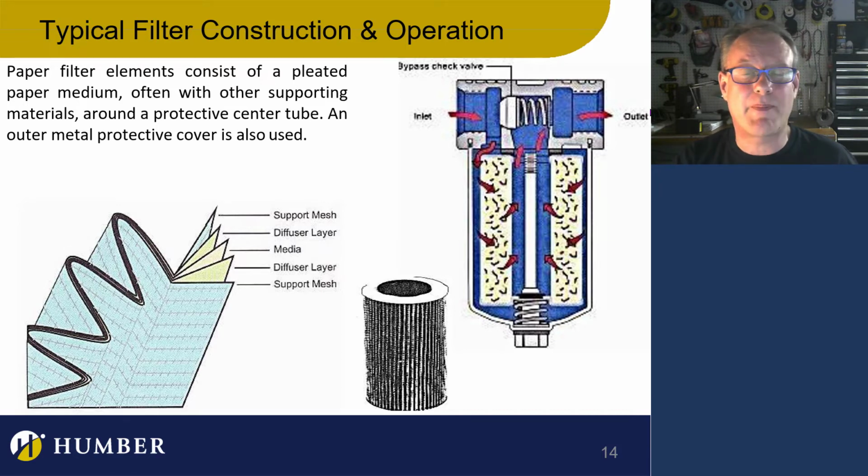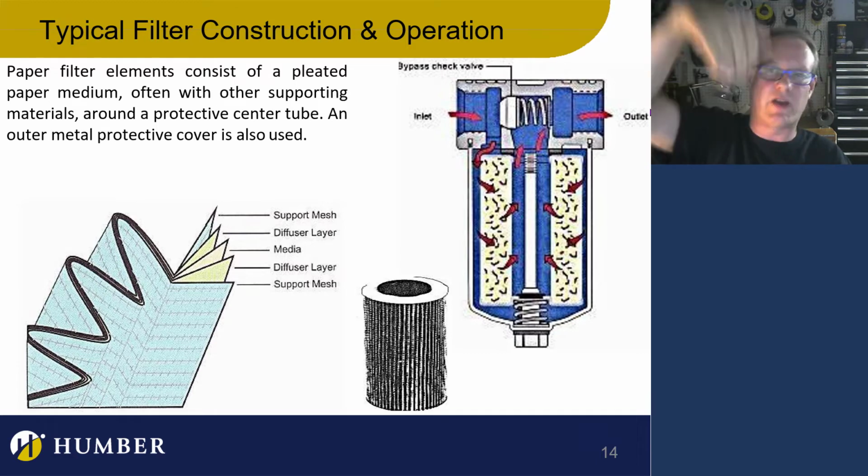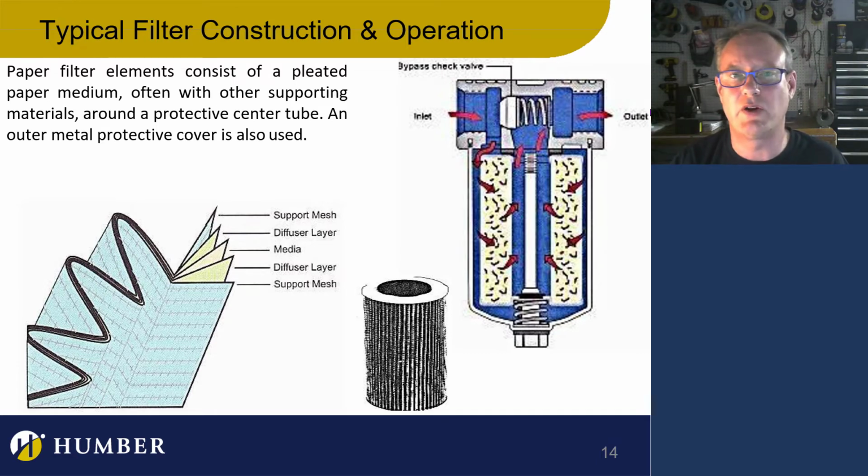But if that happens, you want to run it only momentarily, just to at least extend or retract the cylinder, or to maybe run the system for a few more minutes until you can get a proper filter in, or just until the shutdown of the system can be maintained properly. Especially if you had a heavy equipment machine and the filter's gone, you're like, okay, I got enough in here to drive it, to park it, and to lift up the cylinder, lift up the excavator, remove it, or do whatever you have to do. But essentially, you do not want to operate a system if this check valve has gone.